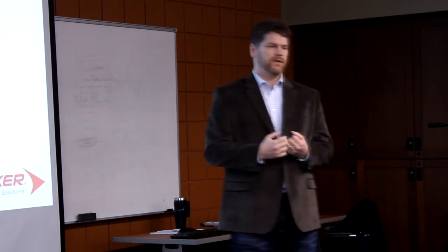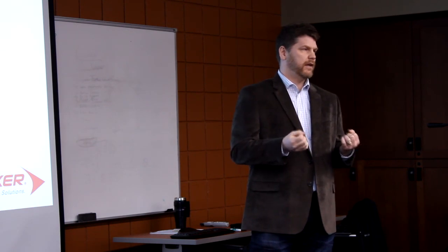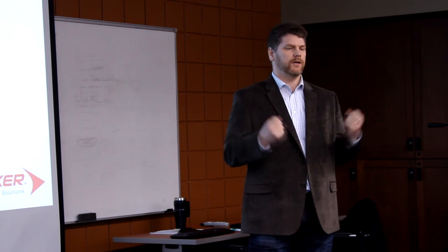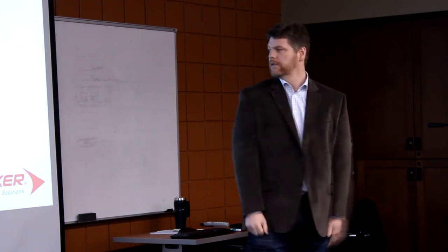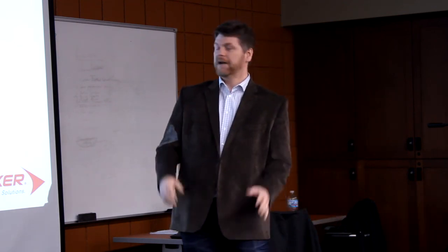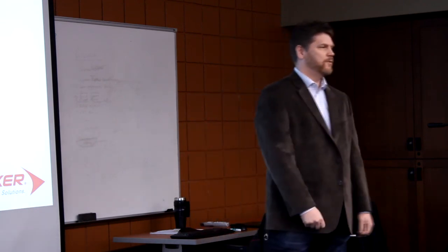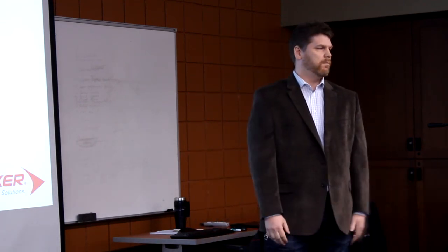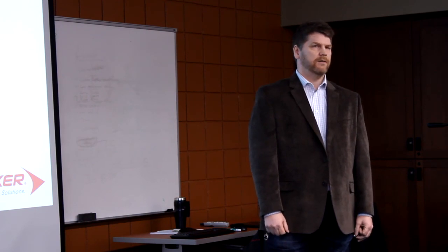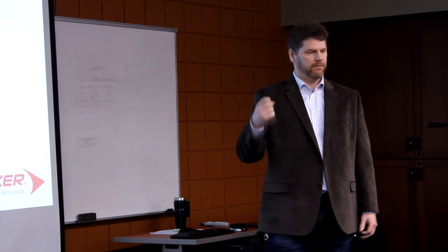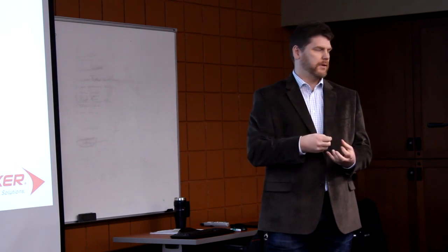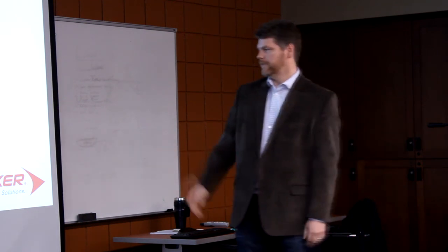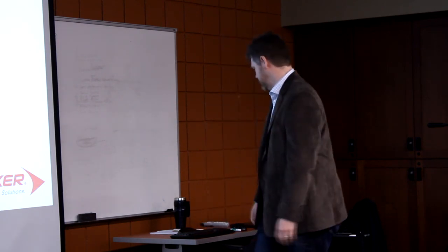In amber, almost all the blue is not filtered but re-emitted from the phosphor as pure yellow light. So on a high level, those are what LEDs are. Most of our LEDs are all surface mount, modern type LEDs. In the old days, we used to have a lot of T1 3/4 through hole type LEDs. We don't use any of those anymore. We're mainly using surface mount LEDs.